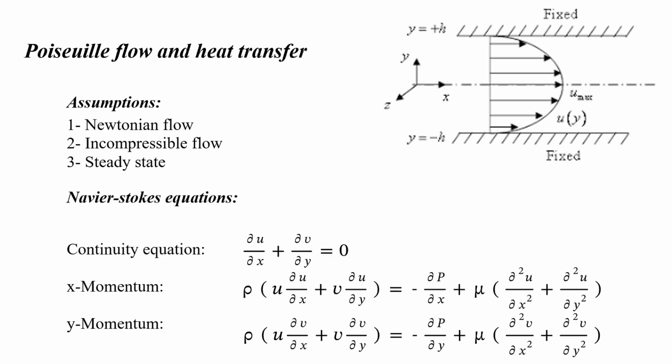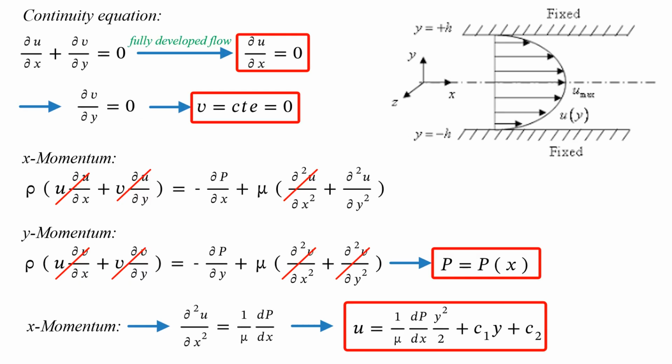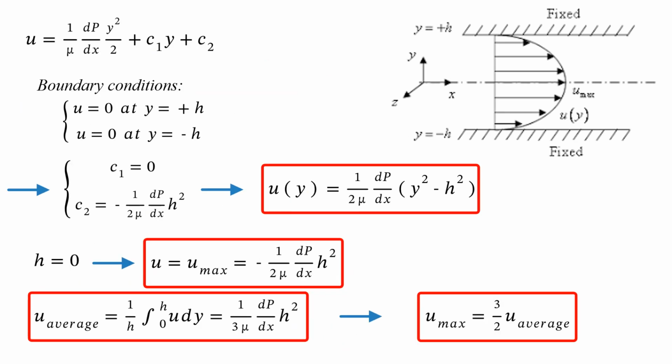As our first project, we will investigate the Poiseuille Flow, and we will solve this problem using theoretical solution and Navier-Stokes equation. Now, if you've followed our theoretical solution, as you probably know, the most important result that we can elicit from this solution is that the maximum value for our velocity happens in the middle section of the channel, and its value is equal to 1.5 times the average velocity. Now, using numerical solution and using Fluent software, we are going to extract the same result that is shown here.